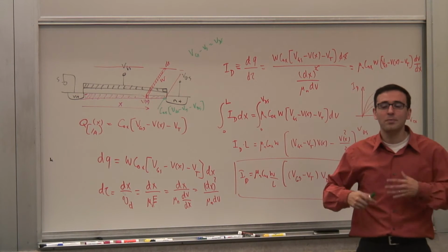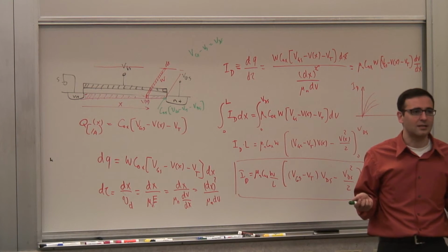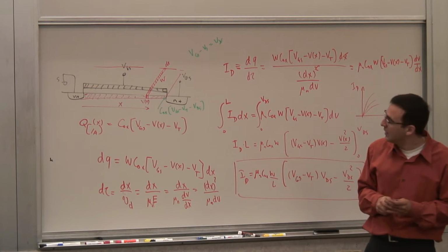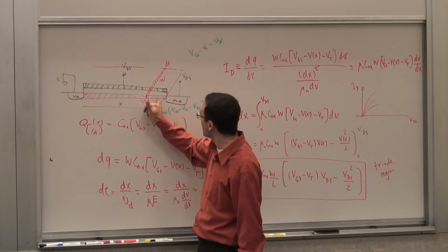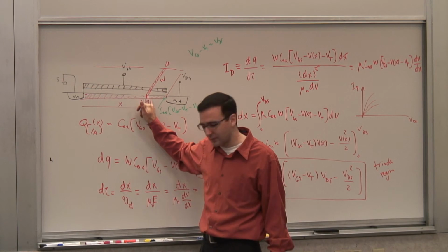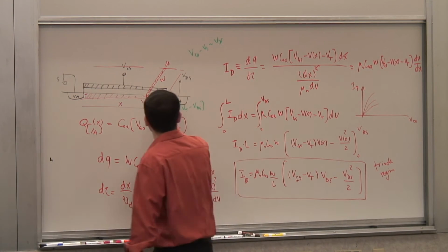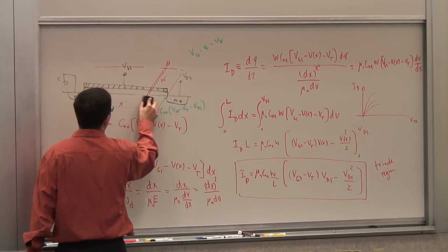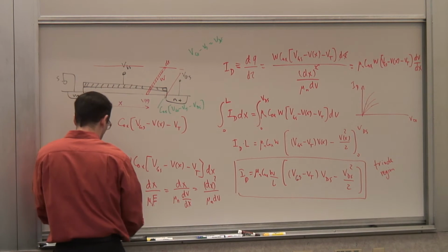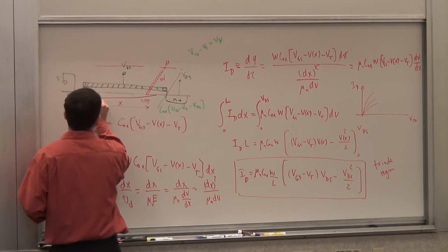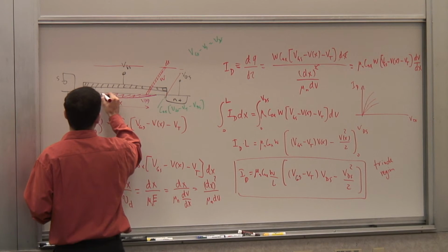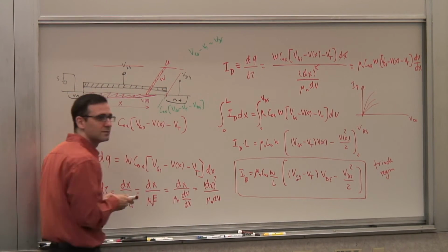Now, what happens if I go above that? If VDS goes above that, what happens? Well, not only at this point, but also at some point beyond it, I will have no surface charge density. So again, symbolically, I can show this new channel like this. So this is the inversion charge, and I don't show anything here.